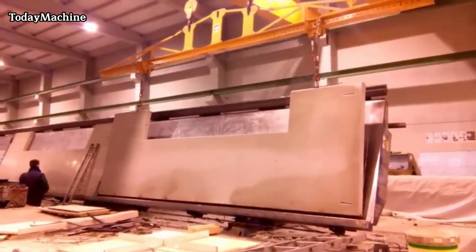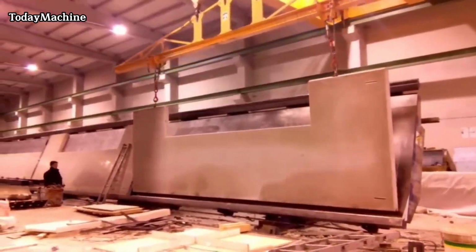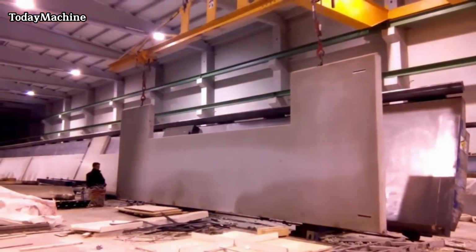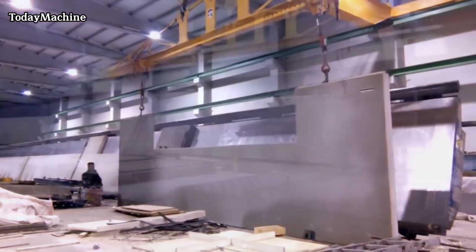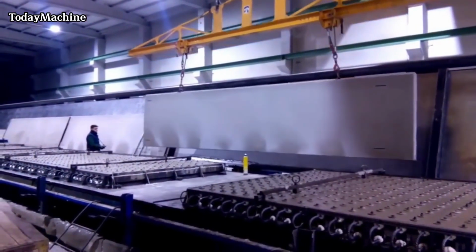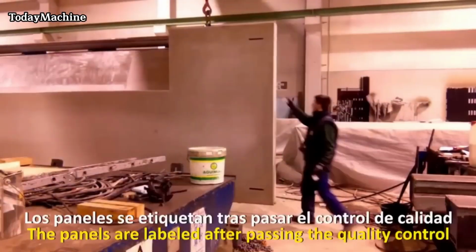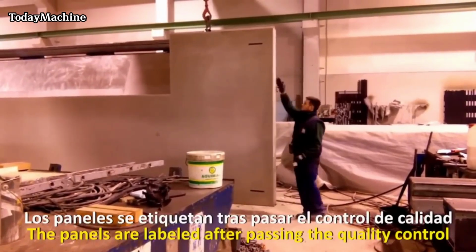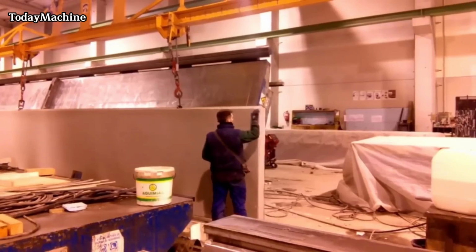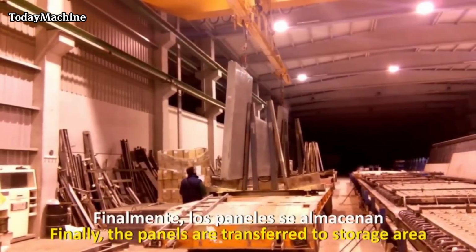The final stage of the manufacturing process involves the transfer of the precast panels to a storage area. This storage area is typically designed to accommodate the panels while they undergo further curing and quality checks. Proper storage conditions, including temperature and humidity control, are maintained to ensure that the panels continue to cure and develop their strength over time. The panels are organized and stacked in an orderly manner to prevent any damage during storage.